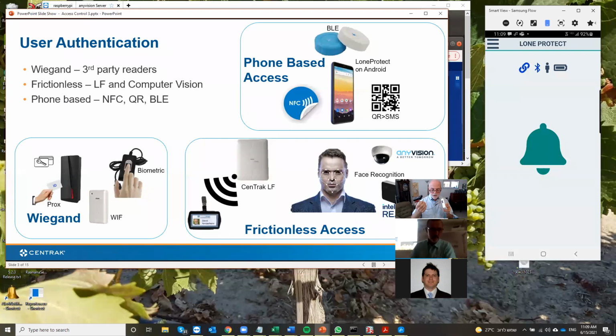Here I've got this reader, which in this case reads NFC cards. I bought it on AliExpress for about 20 bucks. It talks Wiegand 34. It goes through this cable into the Elpas Wiegand interface box, the WIF. That goes on RS-485 to the ELC, right? So we've got a third-party reader talking Wiegand 30, Wiegand 34, Wiegand 26. And then we've got 6 wires actually, 2 for the Wiegand, 2 for the power from the WIF back to the reader. So you're powering the reader.